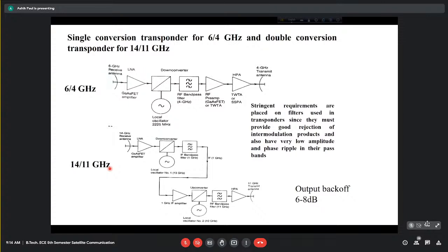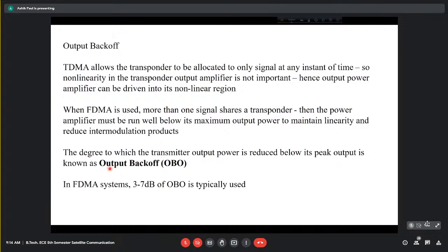So that's why usually the communication satellites have their frequencies allocated starting from around 4 gigahertz or 6 gigahertz. And then again, the frequency pair around 14/11 gigahertz once again suffers from some disturbances which arise as a result of the water vapor related absorption around 11 gigahertz. So, moving ahead, we had also talked about the fact that